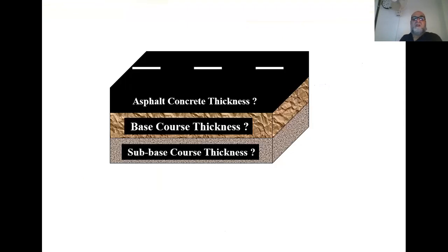So when we design a pavement, we mean how much asphalt concrete there should be for a given traffic in terms of load and magnitude, the climatic condition, and the type of material that is being used. So the only question mark is the thickness of the various layers. And sometimes this also determines whether an extra layer is needed or not.